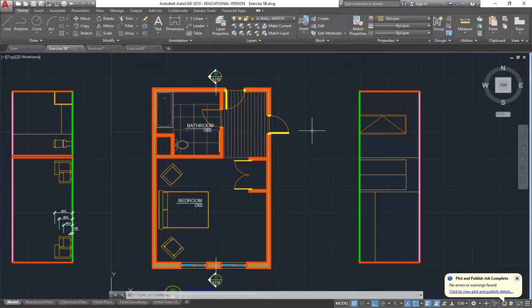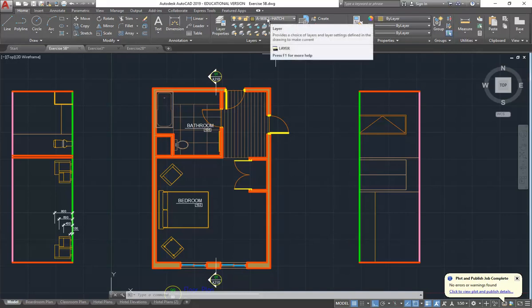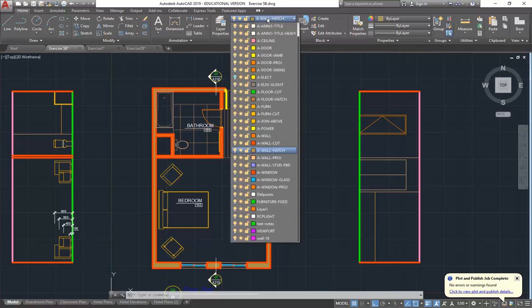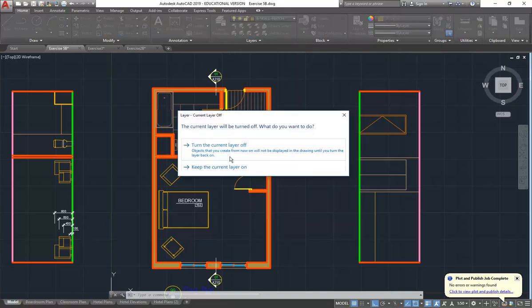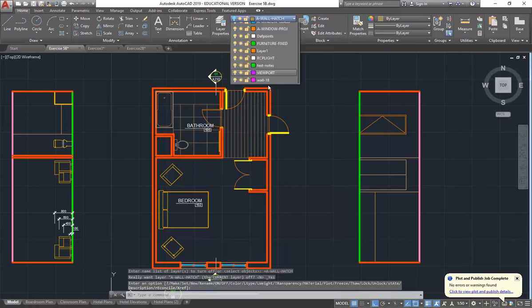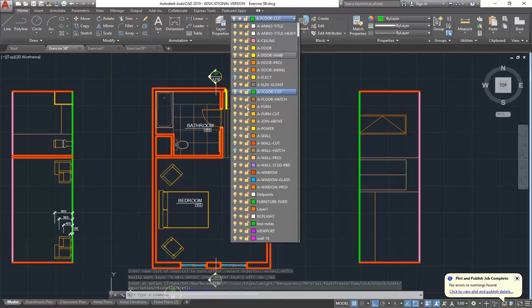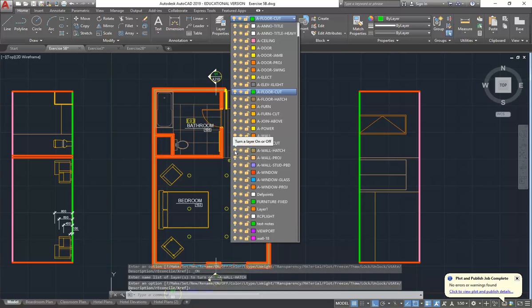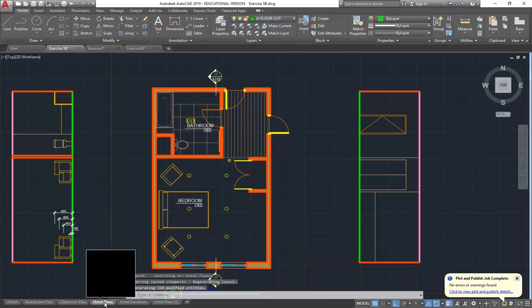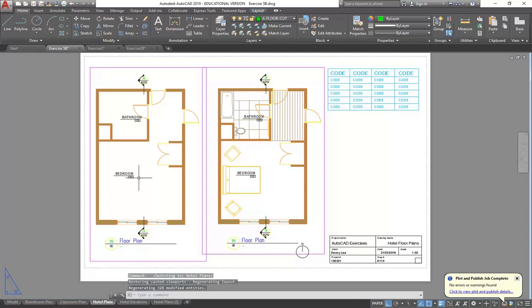And then if there's a problem with the hatch, again, because it's on its own layer, it's much easier to isolate that problem, and if I have to, I can easily delete the hatch or just turn it off if necessary, which again just makes the management a lot easier. So again, having that, oops, sorry, not that one. So let's go back actually, but so there we are. So yeah, it's a really important tip. Try and keep your hatches on their own layer. And so again, that's all, I think, finally starting to look complete.